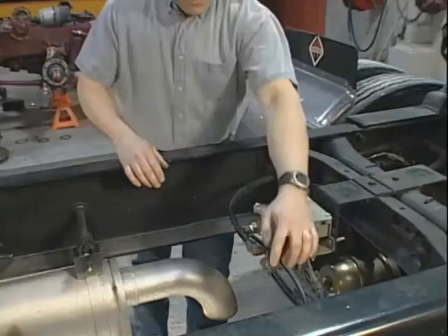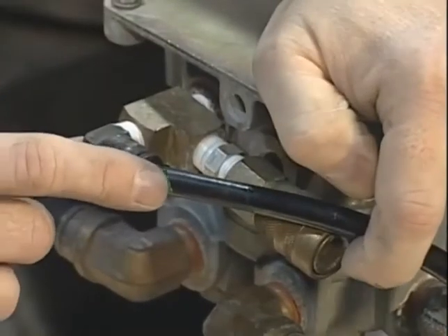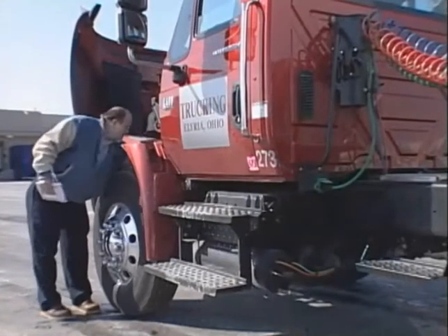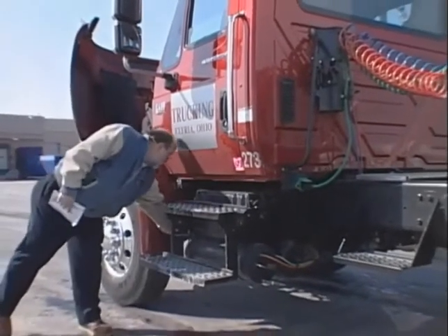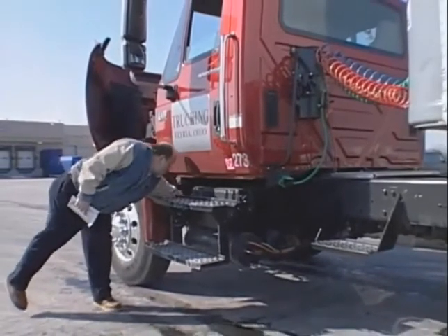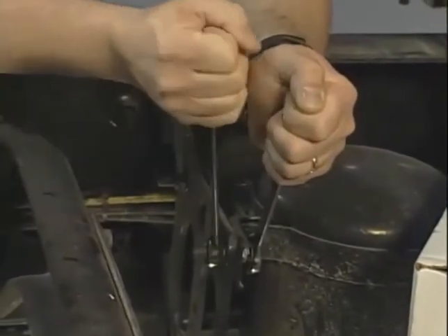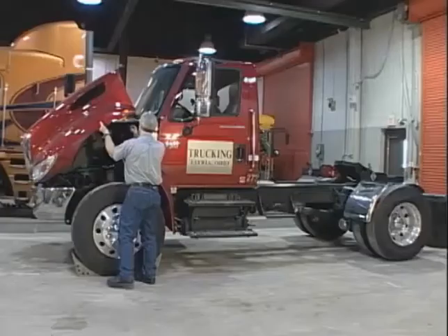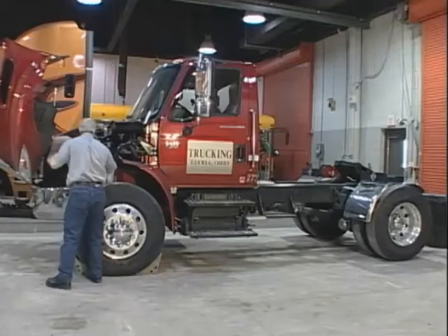Do you always know if there is air leakage? Well, the indications can be very obvious, something you can see or hear. They can also be less obvious, like a driver's comment about how something feels. That's why checking for air leakage is a critical part of any pre-trip inspection. It's also recommended after any air brake system repairs or replacements, and it should definitely be part of regularly scheduled air brake system maintenance, along with draining the reservoirs and other procedures. You can learn more about proper system maintenance in other Bendix training materials.